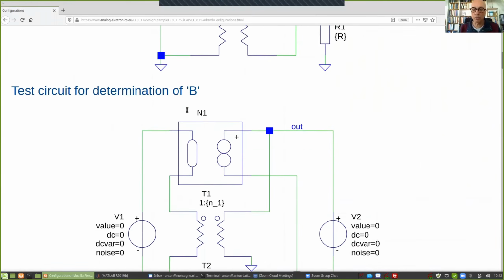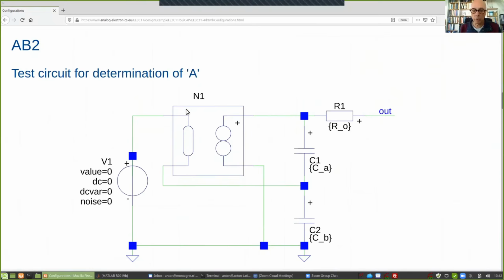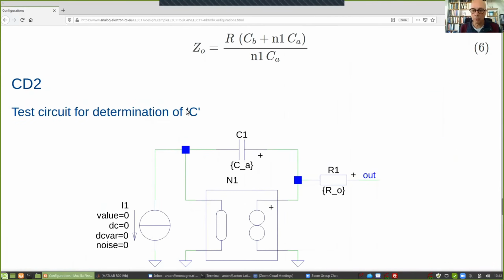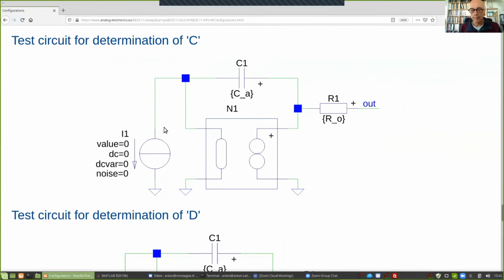Now let's go to a version in which we use the current. And for example, this simple one. If we use the current, so here is the antenna capacitance in parallel with the source, of course, and then you could say here we have our ESD device, but now it is at the input of the controller, and the input of the controller has zero input voltage if the loop gain is very high.